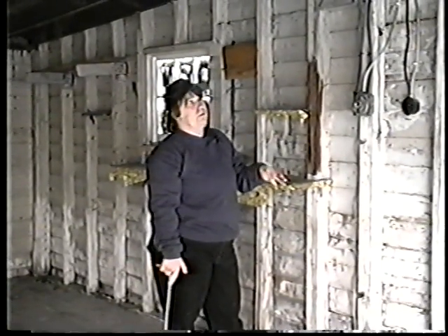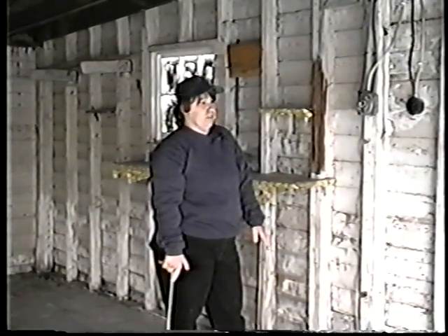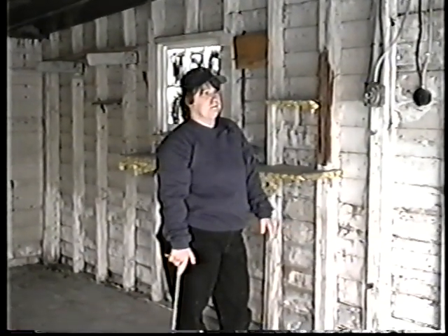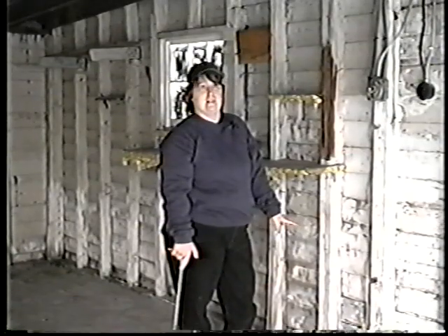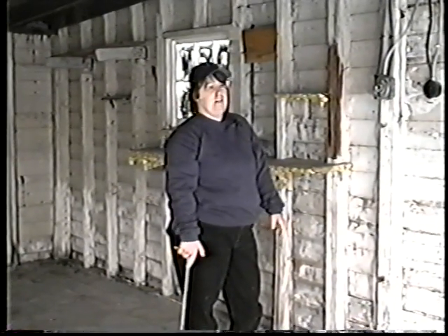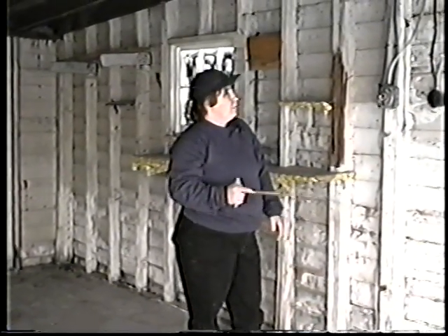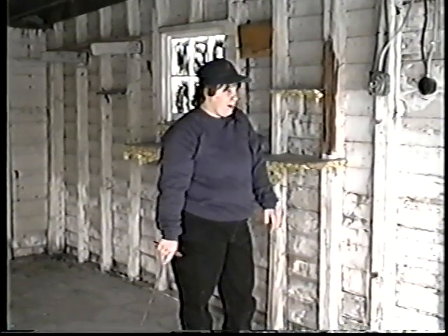It's common to have more than one problem in a situation, because if the wood's damaged and the wood is what we call 20% moisture content or more, you're going to have different insects that are going to want to live in it. So make sure you get an inspector that takes the time to poke and prod and doesn't just walk through.